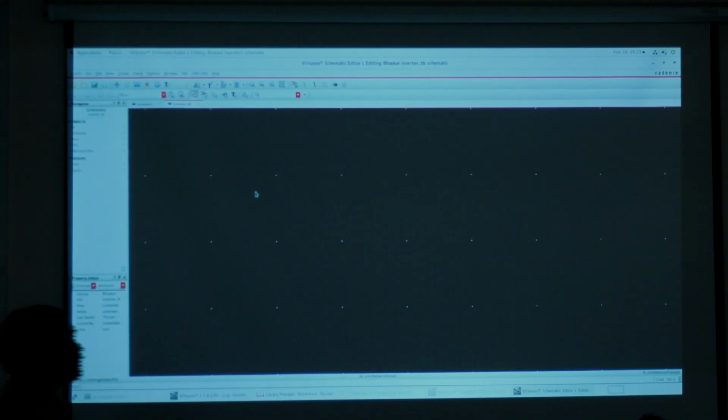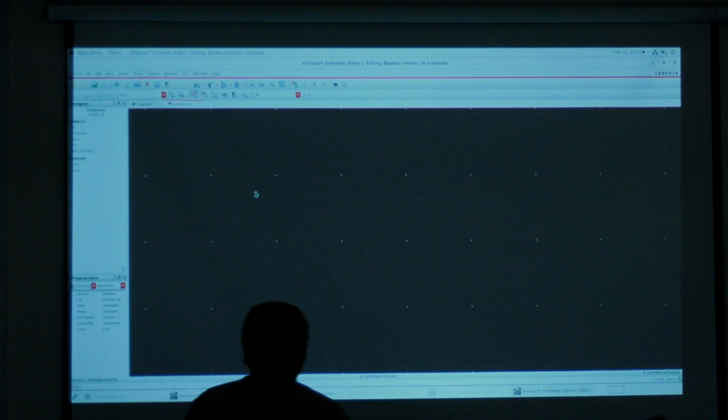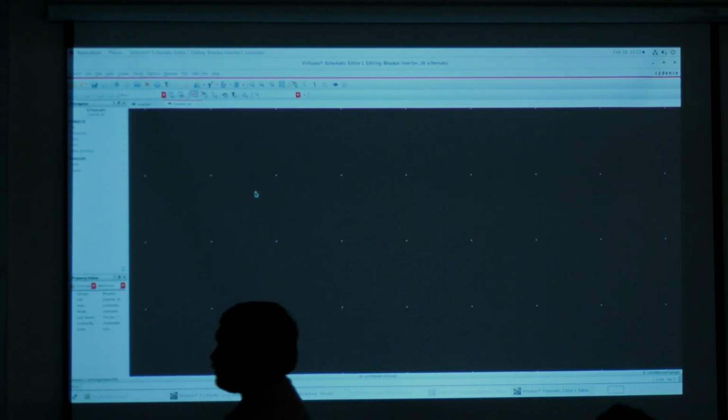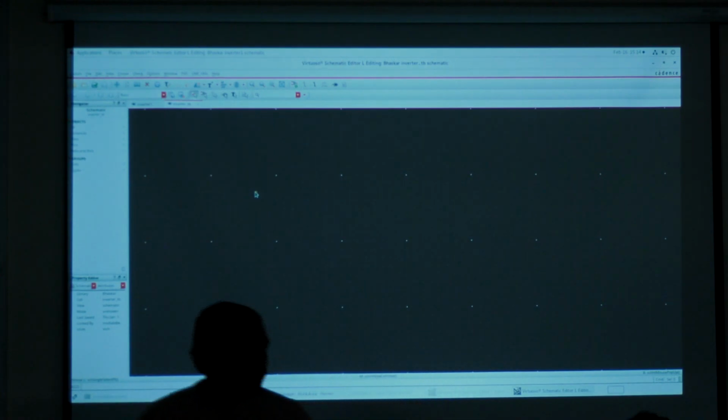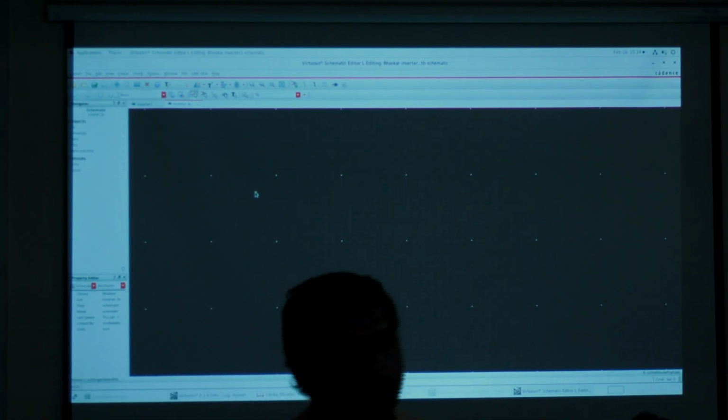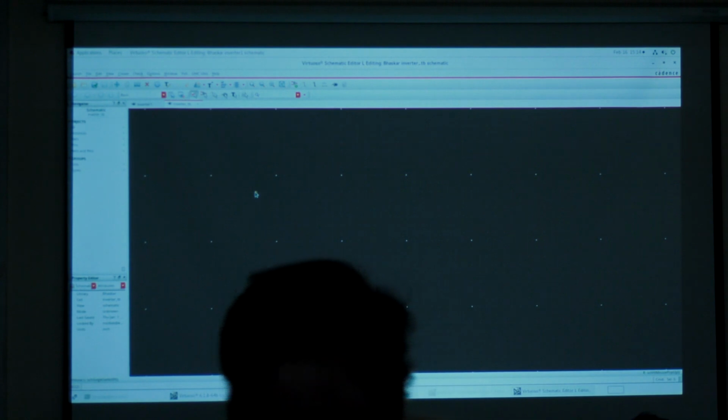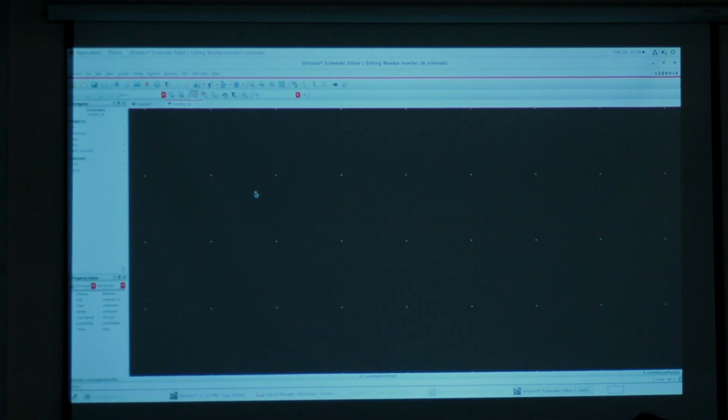You will get another pop-up window, schematic window. Now we created the symbol. For that one we need to create a test bench to see how the inverter is going to operate. I think everyone got the new window, no? Okay, okay. Underscore TB to identify it is a test bench.